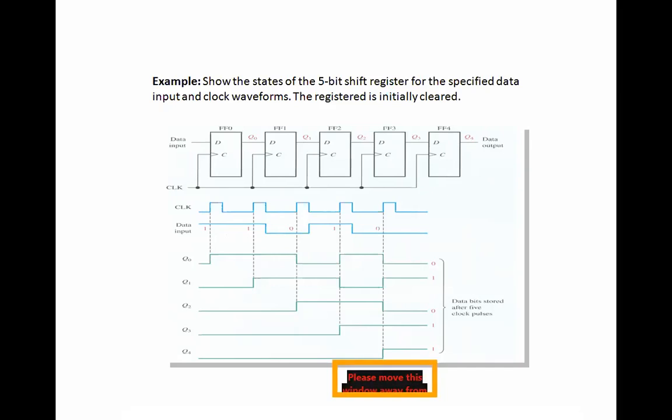Once you have that, you can think of analyzing your data. So I have my clock signal. These dotted lines show whether it is happening at the positive edge or the negative edge. Positive edge, yes, which means the values are moving from lower to higher. So Q0, Q1, Q2, Q3, Q4, which are 0, 1, 2, 3, 4. These are our outputs.